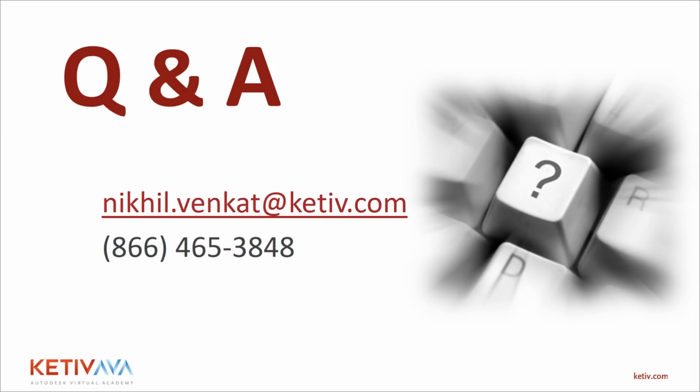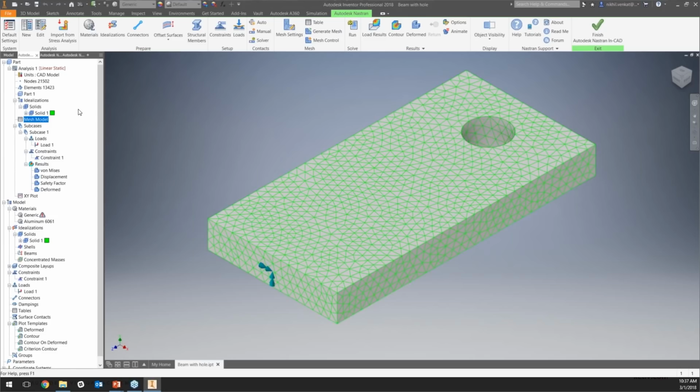All right. This is a great question from Jake. What are the main differences between Nastran In-CAD and the built-in stress analysis tool in something like Inventor Professional? So Inventor Pro is very basic. It can only do linear static analysis in terms of structural analyses. It can only do linear static and modal analyses. Nastran In-CAD, on the other hand, can do a lot of stuff.